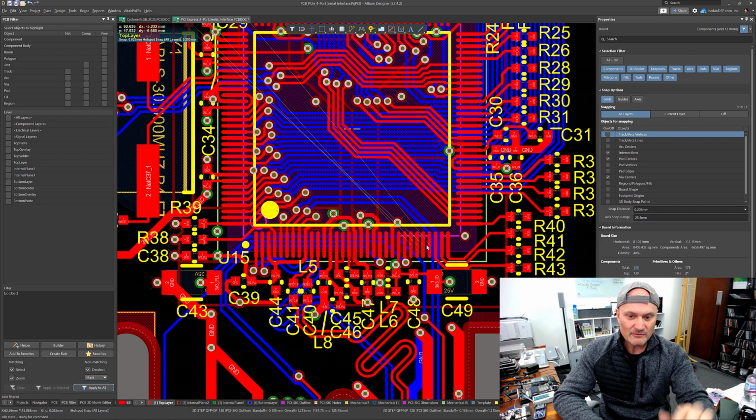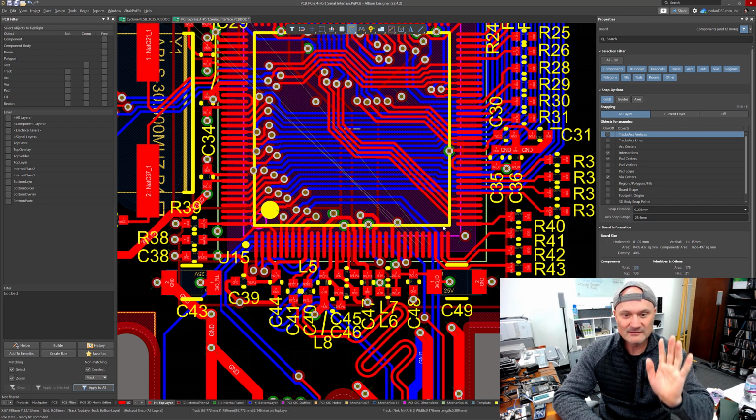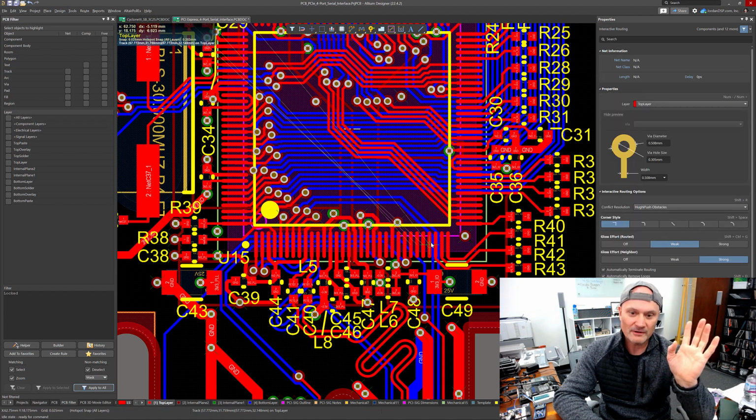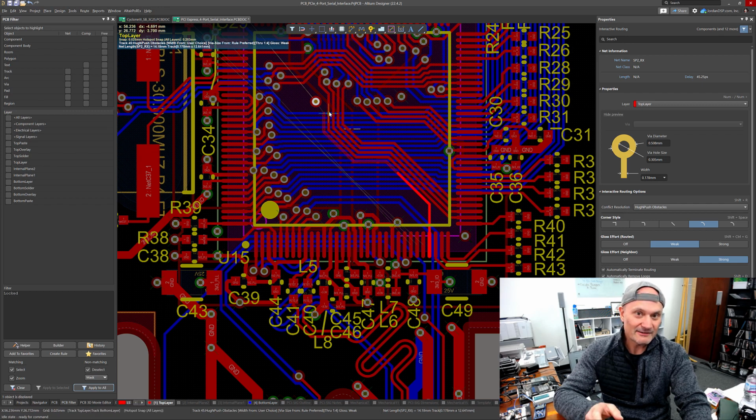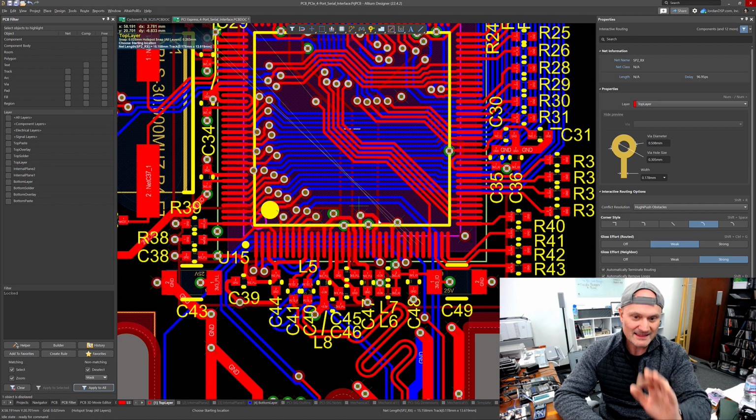So I have a design here with a few unrouted nets. Now, here's the quick, basic thing you'll do in the 101 tutorial, and you won't understand why it's working. I'll start on a pad that needs to be routed, and there's a certain trace width that comes from design rules. If I'm hugging other nets in my design, it's maintaining a clearance that's also coming from design rules. And here there's a via already placed for this one, so I'll just terminate that there.